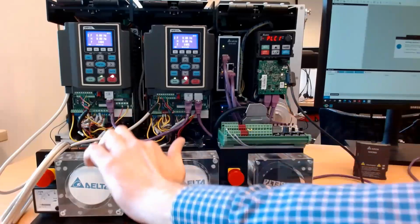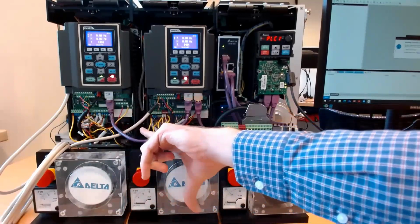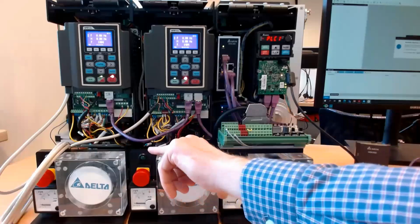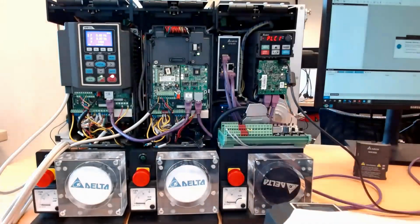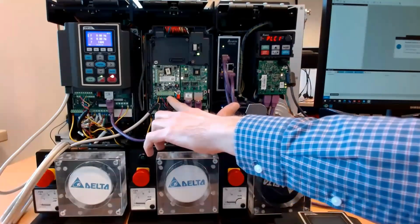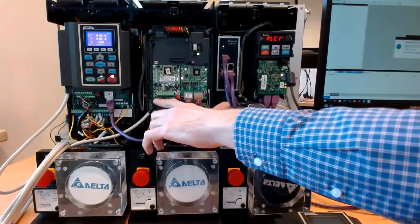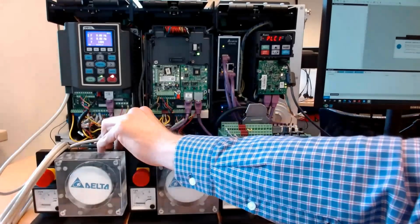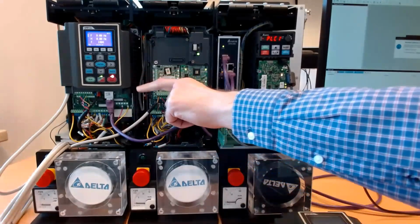So both drives are running in field-oriented control, PG, so that's closed loop, and both of them are running a PM motor. Now all PG cards have different terminals. So you have firstly PG1 for connecting the motor. You have PG2 for connecting an external source of pulses. And then you have PG out, where you can get pulses out to another drive.